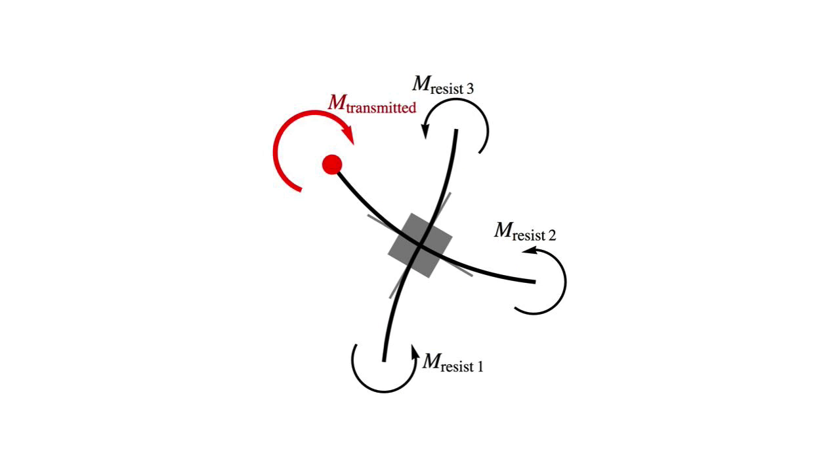Notice two things. The curvatures at the ends are consistent with how the transmitted and resisting moments are acting, and at the same time consistent with how the overall members are deforming. The second thing is that the angles at the connection remain 90 degrees, which is the way they initially started, but now the whole joint rotates as one unit.